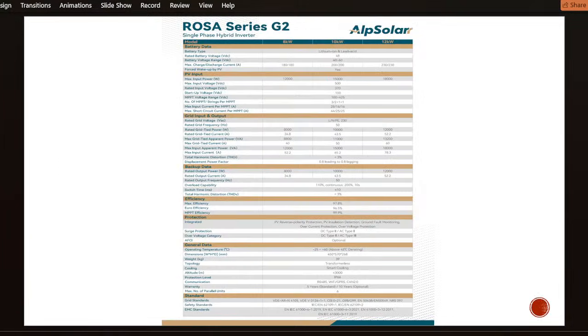The number of MPPT per string: it has 3 MPPT, like was rightly said, but the first MPPT has 2 strings. That MPPT is the biggest. Don't forget when I was arranging the power, I said the first MPPT can take what? 8,400. So it means it has more strings. There are 2 strings that are internally paralleled inside that first MPPT, while the remaining MPPT have just 1 string. So in total, this 12 kilowatt inverter has 4 strings that you can parallel together.